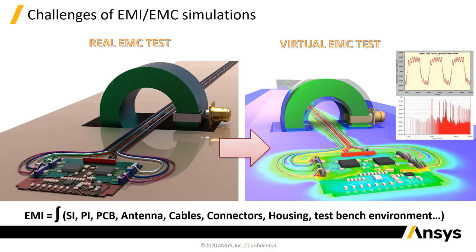Just like in the lab, we do have some challenges on EMI EMC simulations. Here we have an example on the left side of a real EMC test. It's a bulk current injection test. And on the right side, we have pretty much the same test, but now in a virtual environment in HFSS. We run the same test, but now virtually. So you don't need a physical prototype.